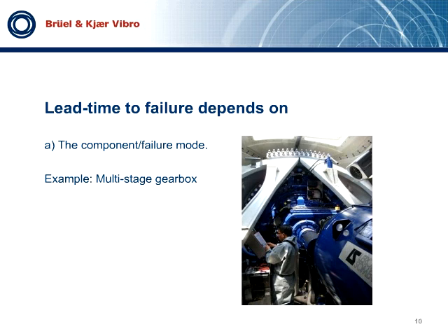We're of course not interested in knowing when the component fails completely, because that would not exactly be proactive. You know, I've seen gearboxes run for 8 months with broken teeth, where no secondary damage is introduced. And I've seen the same thing happen in weeks, where the neighbor teeth and the gears just get completely blown out. So planning a good lead time, or predicting a good lead time, is something that is extremely difficult.